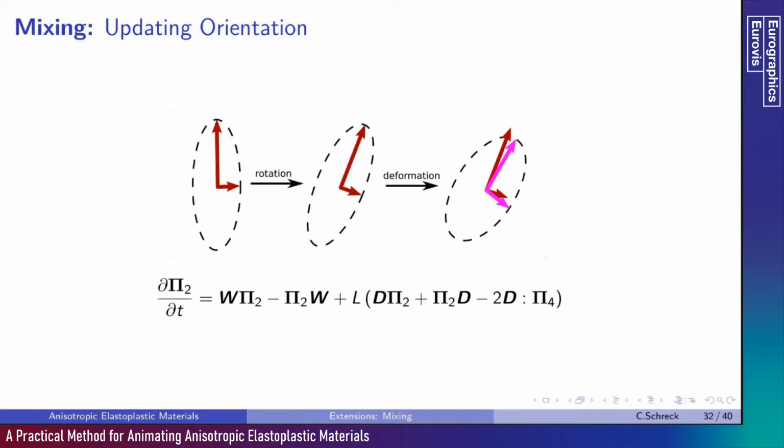This formula is usually used for fibers in suspension in a flowing fluid. So we have a rotation part, where the objects are just rotated with the flow, and a deformation part, which takes into account the grain's tendency to align with the flow, and also the collisions between the grain. These formulas seem to be a valid approximation of what's happening inside the pile, but further studies will be required to really understand the mechanism inside the material.